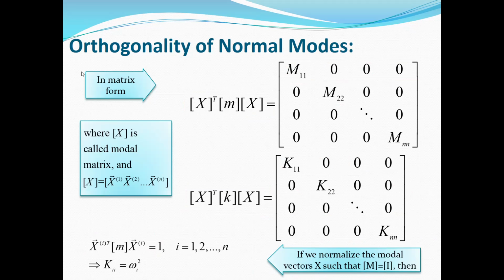From here, you can obtain the amplitude, because you know that these vectors are functions of, for example, x1. For example, in the system with 3 degrees of freedom in the previous example, we found that the mode shape was, for example, 1, 0.2, 0.4 multiplied by x1. This is the first mode shape.